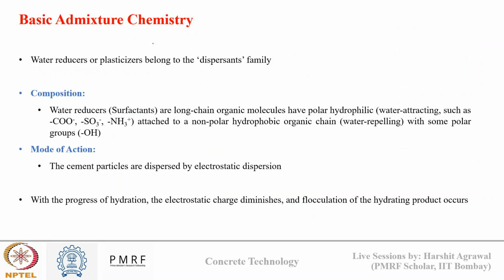Now, what is the science behind these admixtures? How are they able to disperse cement particles? How are they able to act as a water reducer? These water reducers or plasticizers generally belong to the dispersant family. Their composition has a water reducer which is known as a surfactant. They have a long chain organic molecule which has a polar hydrophilic tail attached to a non-polar hydrophobic organic chain with some polar groups.